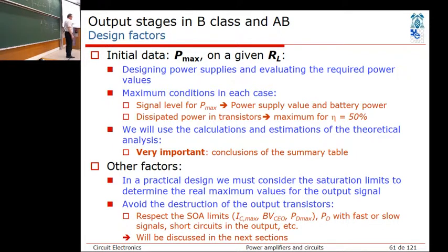What happens if you are running this as, say, a voltage follower for a motor drive or something like that, and you run it constantly with that maximum power dissipation? Then it changes a little bit, right? So it doubles. Then in steady state, it doubles the power consumption on the transistor.